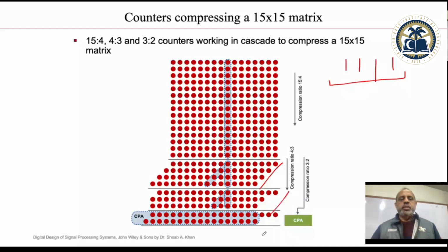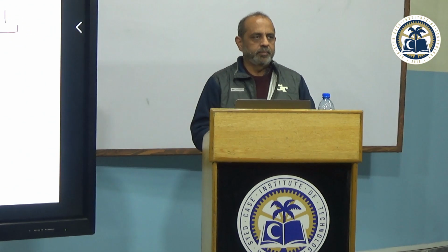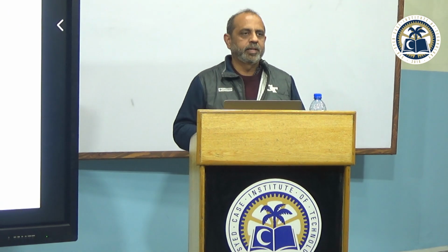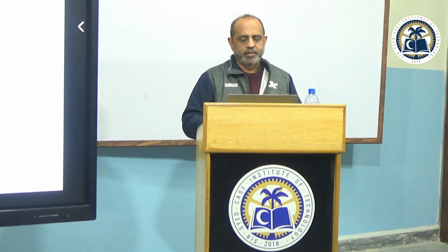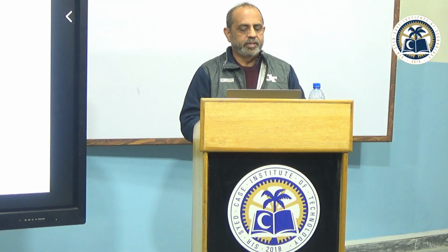So this concept of compression is widely used in digital logic, especially once we are converting algorithms into silicon, making hardware. If you are adding 15 numbers, putting 14 full adders like a carry propagate adder does not make any sense. Just compress them first, where you are not propagating the carry, you are just saving the carry and putting it at its appropriate location, and that is very effective.